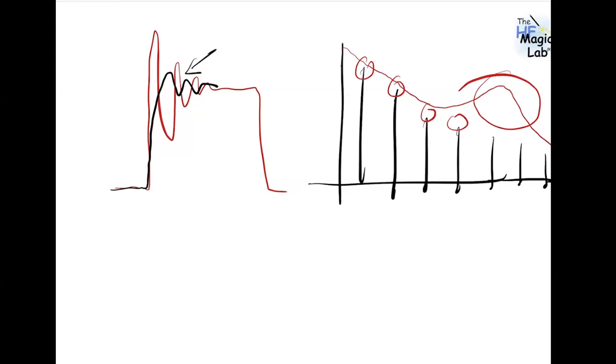So you can have a peak that is at some value, but it's not repetitive or happens only after a long time. So quasi-peak usually is a measurement that takes more time. For debugging, my recommendation is to use the peak detection. If you pass in peak, you will pass in quasi-peak. That is the idea, and the peak detection is additionally faster. You have a lot of books, application notes, and references where you can learn the schematics and the waveforms that you can obtain from these three different detectors.